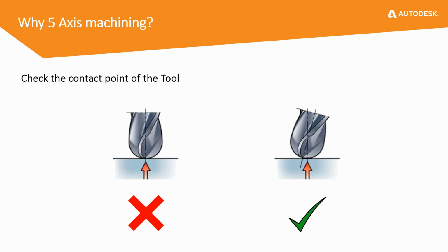It is because of several problems with the usage of ball nose while machining. The first one, by its form, the absolute center of the tool does not have any cutting edge, which means there is no cutting action. In addition, the chip evacuation at the central section is very difficult since the body is practically zero.